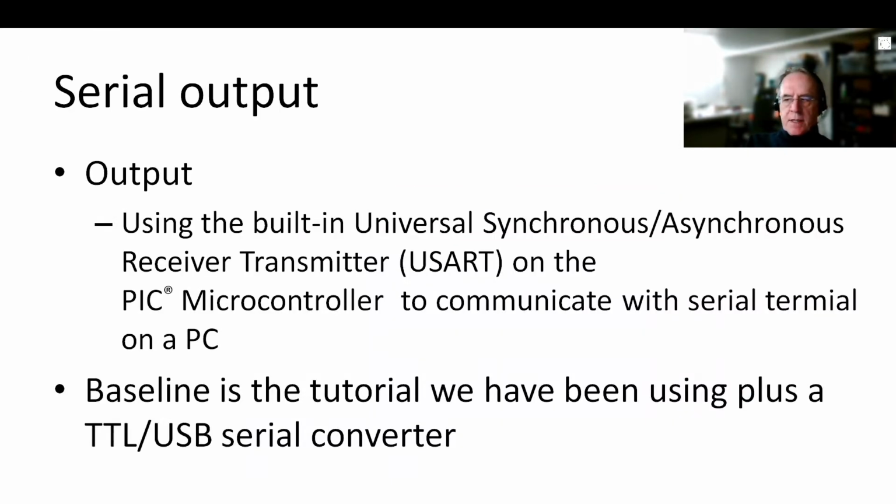So what we're going to be doing is sending some data from the PIC via something that's called the USART, which is the Universal Synchronous Asynchronous Receiver Transmitter, on the inside of that PIC, through a USB TTL converter onto the PC terminal. So I've added in a TTL USB serial converter because it takes the signal from the PIC and then turns it into something that the computer can understand.